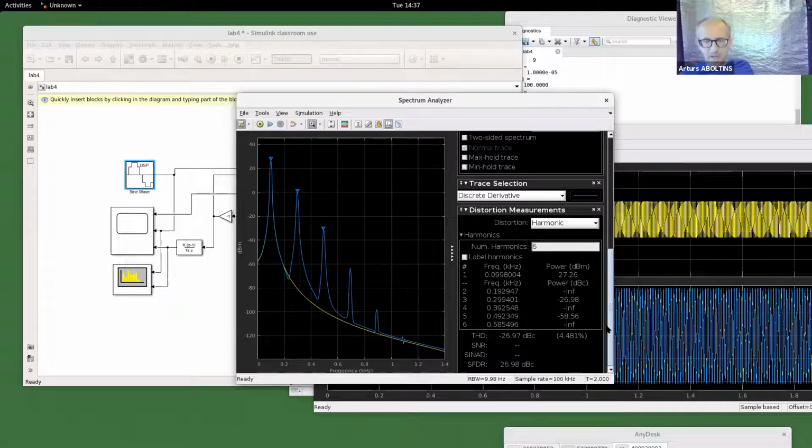Also, I believe even in power electronics, if you have an inverter, it's important that you do not have a very big THD for the generated sinusoid, because your inverter in this case will generate a lot of noise for other electronics, and this noise will propagate through the power supply to, for example, your TV set, and then it will work very badly and can even burn out if you have a very bad inverter.